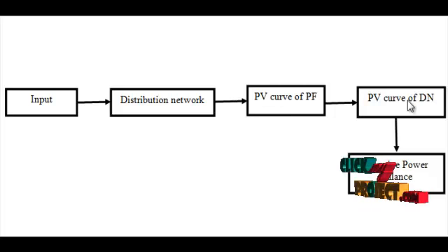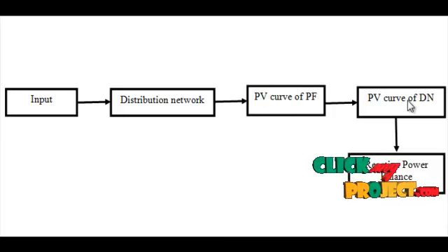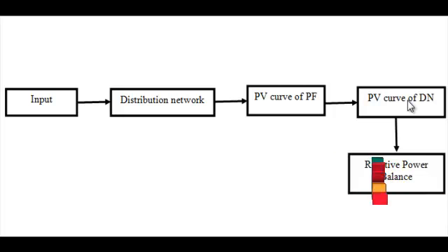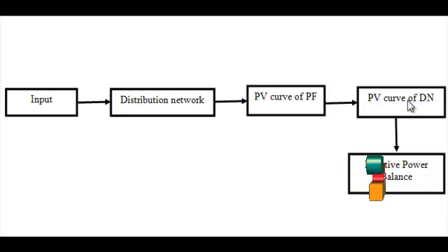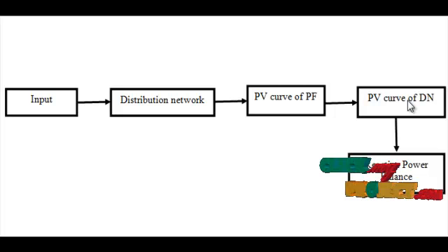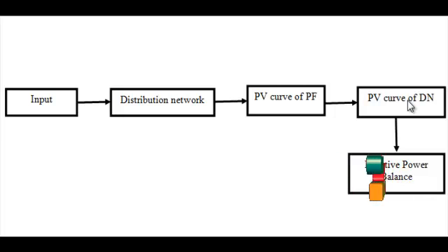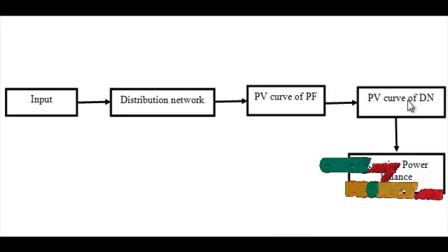Then we draw the PV curve of the distribution network, assuming KQP3 is the ratio of Q3 with respect to P3. KQP3 is a constant with a certain power factor. When the bus voltage is constant, the relation curve between P3 and U3 can be obtained, which is called the transmission characteristic curve of the distribution network, also commonly known as PV characteristics. When the bus voltage is 1.1, the power factor of the load is constant and the ratio of Q3 with respect to P3 is equal to 0.02. Now the PV curve will be drawn with that value.